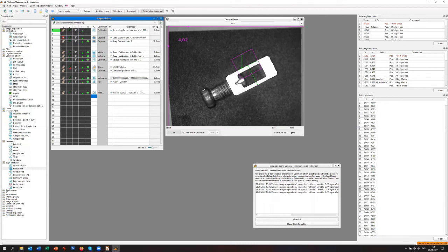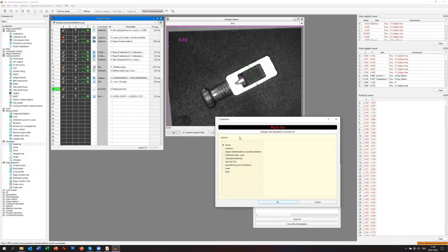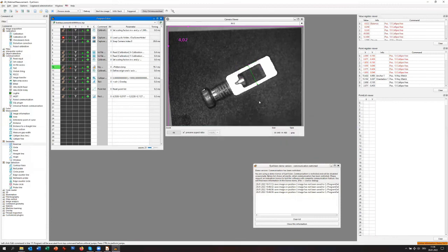In this case, we only want to use these new points, so we have to reset the point list. Therefore, we have this point list tool. It can do a lot, but it can delete the point list. And you see here, if you run the software until this point, the point list is empty, and the next ones are all the new points.